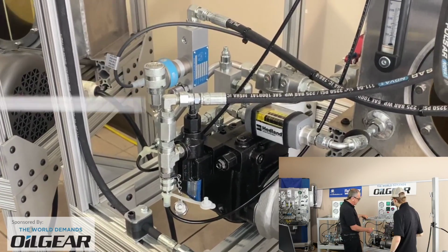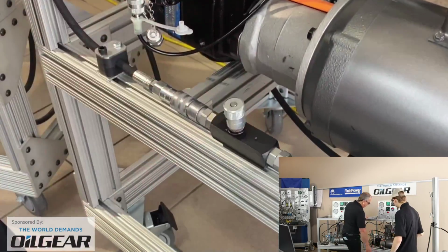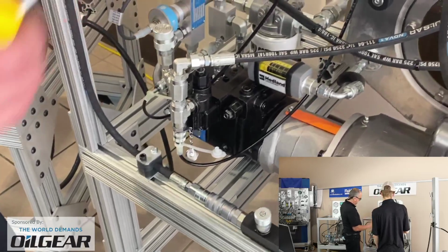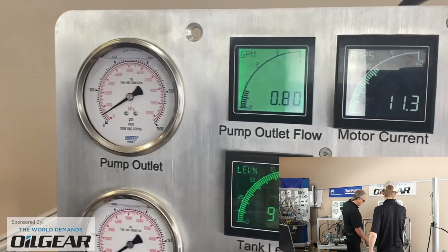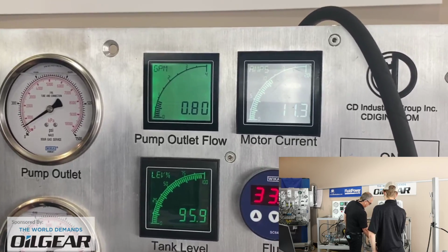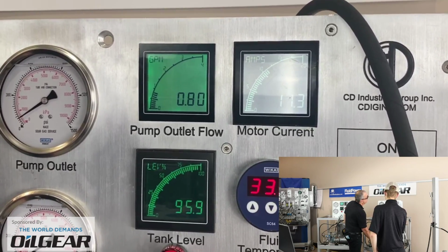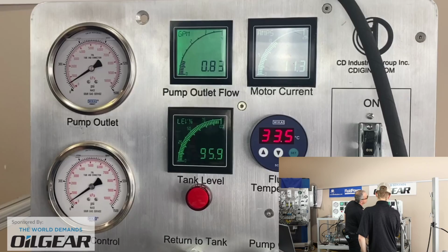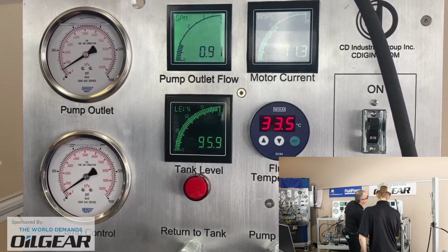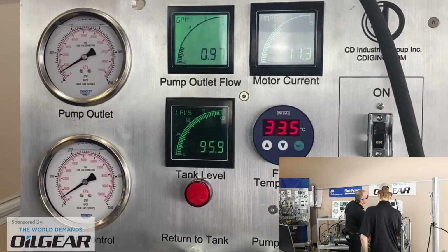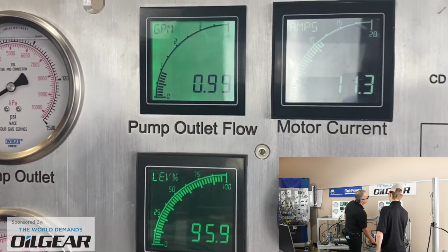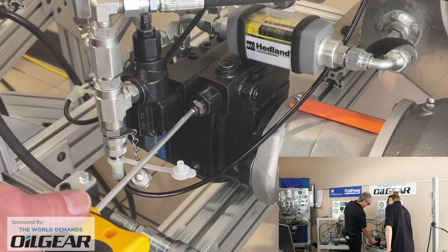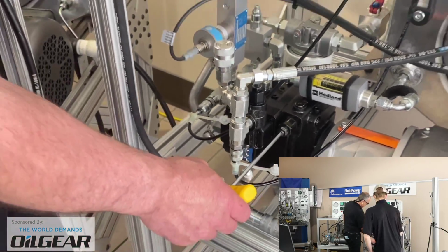So since we've got a nice open flow path, I'll reverse the order of my action this time. Perhaps 0.8 gallons per minute is not the correct maximum amount of flow. Perhaps our pump is supposed to be a little bit larger, closer to 1 gallon per minute. So which way should I go? Should I go clockwise or counterclockwise? Well, as you'll find out, what we need to do to get that pump to be larger is go counterclockwise on the adjustment screw, and here comes our flow. Okay, so we're increasing the maximum flow rate from 0.8 gallons a minute up to 1 gallon per minute, and it was simply a matter of counterclockwise turns on the maximum volume stop.